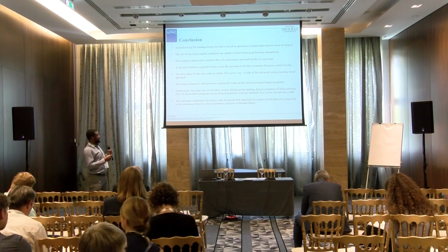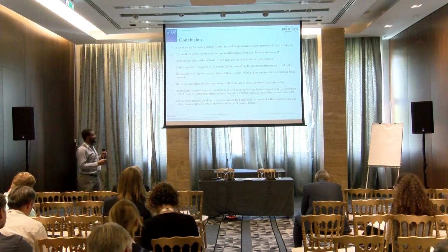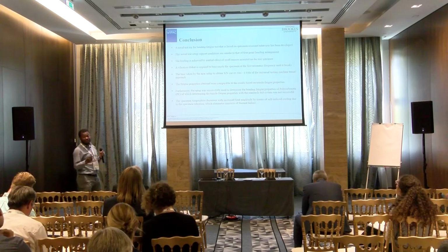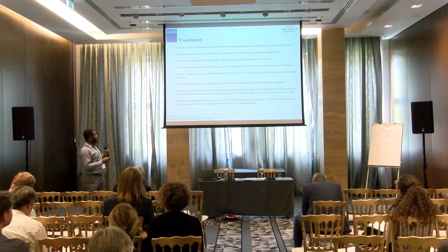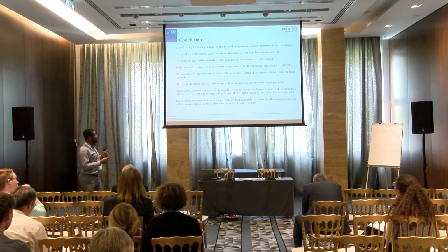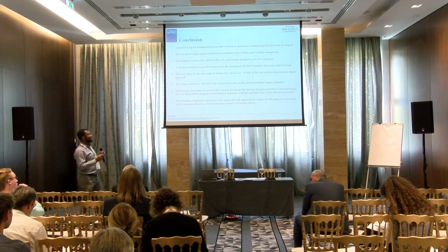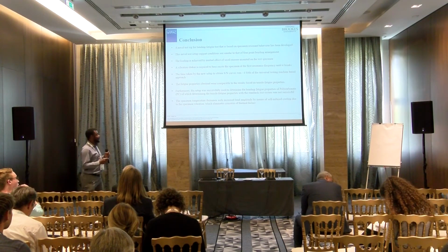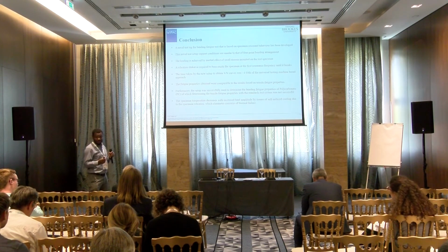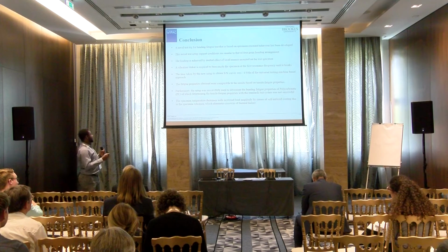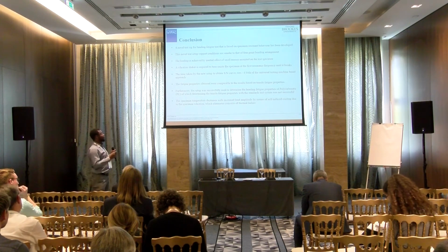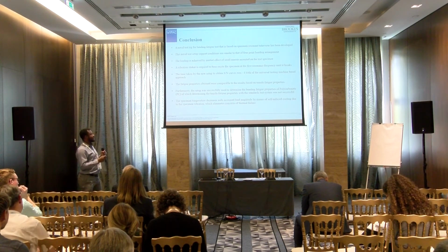A vibration shaker is required to excite the specimen at the first resonant frequency until it breaks. The time taken by the new setup to obtain SN curves was 1/10 of the universal testing machine-based approach. The fatigue properties obtained were comparable to the results based on the tensor fatigue properties.